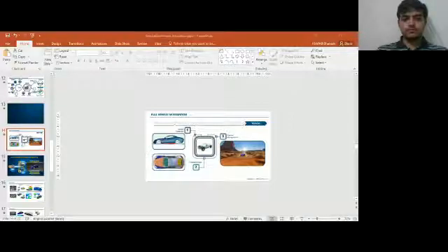Now, how do you do that? If you want to do real-time analysis, you have to look at a man-in-the-loop type of method. We will have the control box, which simulates the control systems inside the vehicle. And we have a setup where you, as a driver, can sit and drive the vehicle, sort of like the simulators you see in some driving schools. The only difference is that along with the simulator is the control box of the vehicle itself.